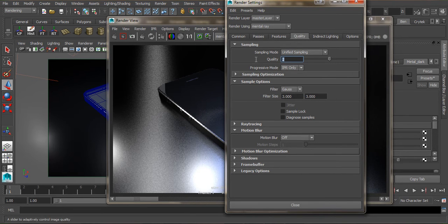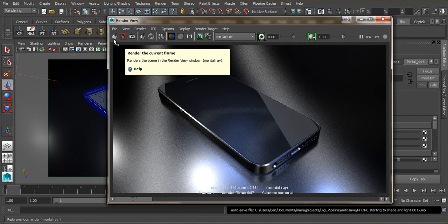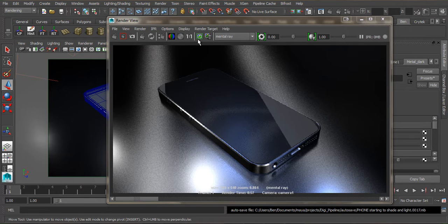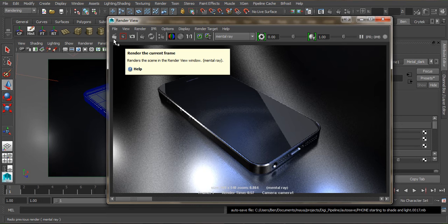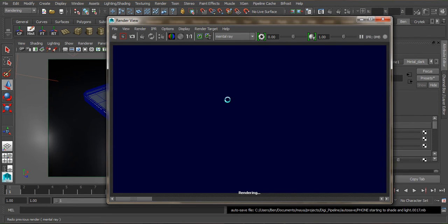But it's going to take about 20 minutes probably to render with the quality set to 2, and maybe about 10 or 12 minutes for the quality set to 1. So once we hit render, now would be a good time to go and do the dishes or something like that. And before you render it, just keep this image so you can see the improvement in quality as well. So go ahead and render the current frame with these new settings.